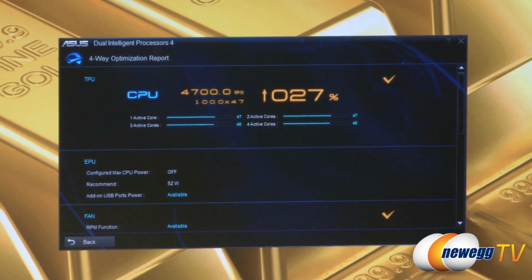Okay. This is a very big thing that you need to factor in, because if your thermal solution does not have the headroom to compensate for this increased voltage, you will have a very high level of heat produced in a very small period of time that could induce throttling, as well as cause instability to your system. Now, for people that are going to use their system normally, such as viewing videos, doing productivity or gaming, it's going to adhere to the voltage table that we've applied as our maximum. So I think we can show this through some real-world examples. Okay. Let's first go ahead and open up AIDA64. All right.